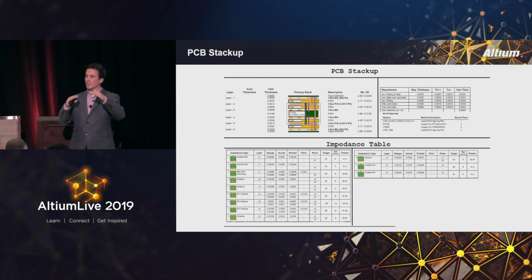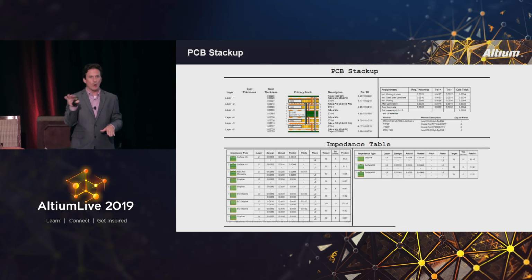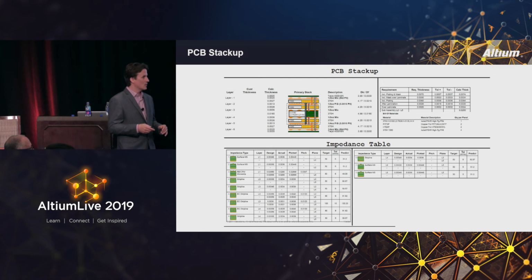What I can do to minimize the bad effects of that is route the traces on my 2 layers perpendicular to each other. And that actually makes the layout easier. If I stick to that rule and say traces on this layer are only going horizontal and traces on this layer are only going vertical, and anytime I want to go vertical, I'm transitioning from the horizontal layer to the vertical, all of a sudden at the end I've fit in way more stuff because all my traces on one layer only go one direction, and it makes things so much easier. You can definitely get a lot higher density if you bias your layers opposite each other.